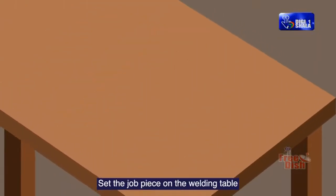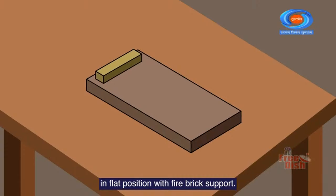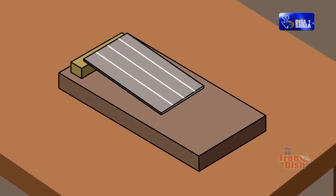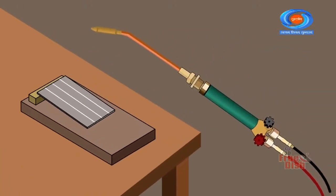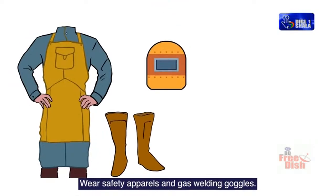Set the job piece on the welding table in flat position with fire brick support. Select and attach nozzle number 3 to the blowpipe. Wear safety apparels and gas welding goggles.